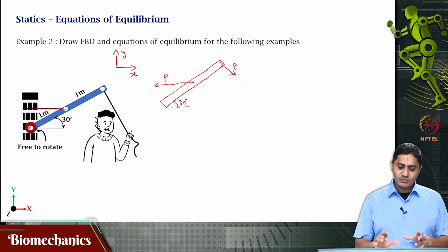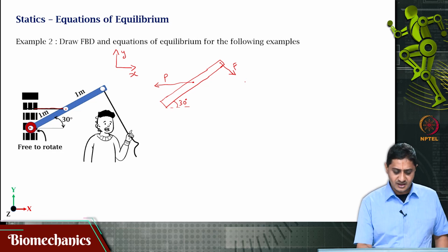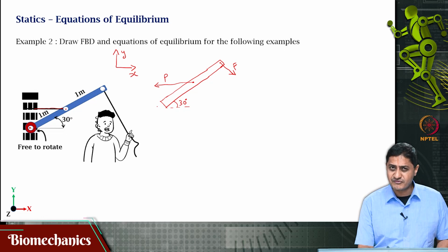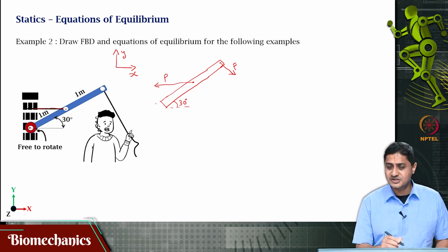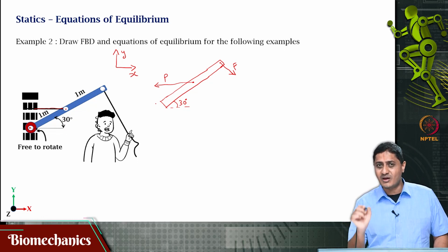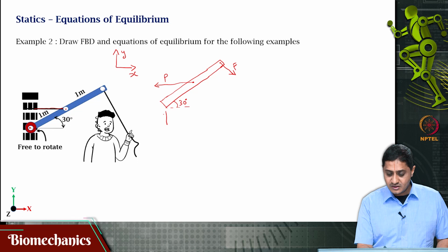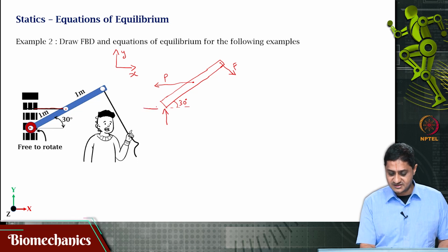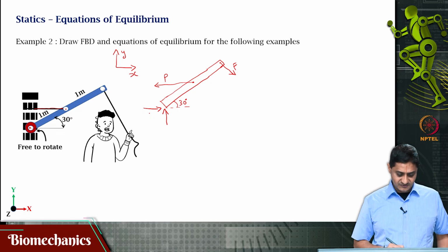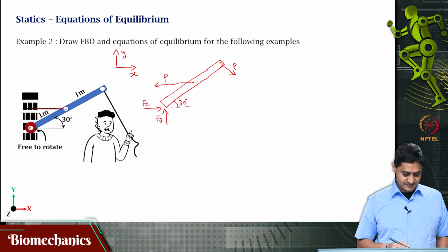We will see that. Okay. So, remember that the force is applied perpendicular to the beam. Okay. And I am removing this because I have removed this beam from the contact at the wall. There are going to be a couple of forces, because the beam, when it is attached to the wall, cannot translate along the x axis and cannot translate along the y axis, because these movements are restricted and only these movements are restricted. Right? It is not restricting the rotation. Because of this reason, there will be two forces, because two translations are restricted. Right? These will be the two forces. I am going to call these Fy and Fx.